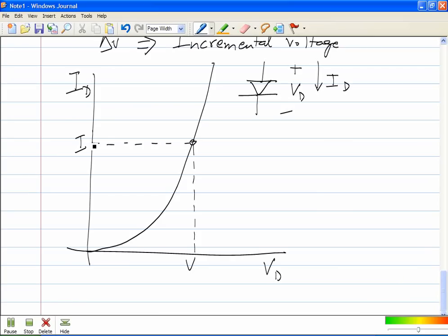If you had a linear resistor, what kind of curve would you get here? You will get a straight line. Okay. So clearly, because it is nonlinear, you get some weird shape. And clearly, you see that when I reduce the applied voltage by a factor of 2, the current reduces by more than a factor of 2, clearly indicating nonlinearity. However, if I change the applied voltage by a small amount delta V, so let me say this voltage is V plus delta V, what do you see?